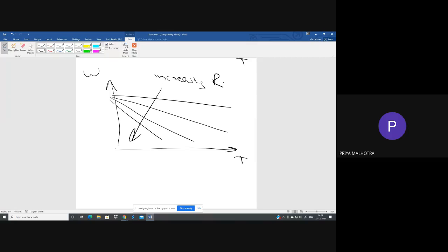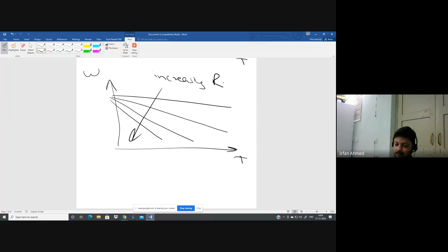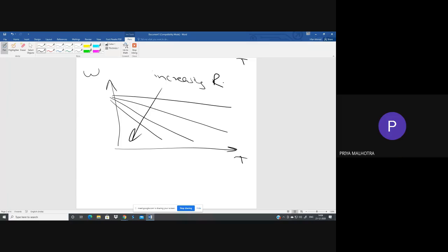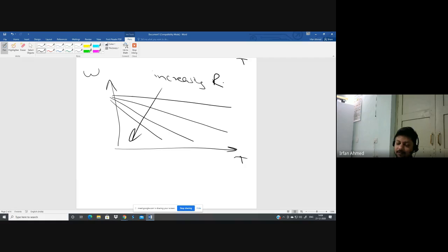No, if you are taking speed, there is a flux also there. In case of a DC shunt motor, I'm saying, clear your concepts first. I'm also talking of the DC shunt motor only. IA is equal to V minus E divided by R.